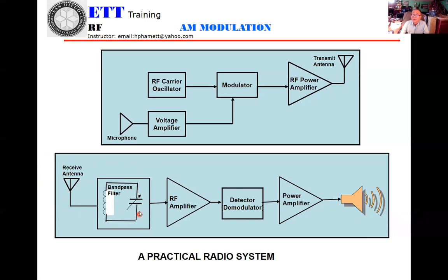And now you have the band pass filter, you adjust the capacitor, inductor, whatever, in order to select the resonant frequency that goes here. And the signal is not good enough, so that's why they need an amplifier. After they amplify, they go to the detector, the demodulator.